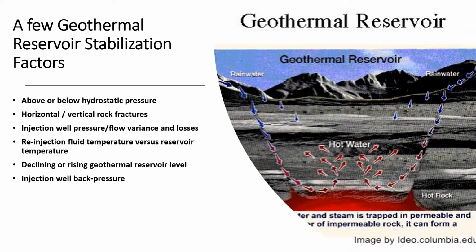Geologic structure impacts how the relationship between injection wells and return wells can best be managed. Injected fluids for reservoir replenishment and stabilization can be lost to fractures extending far beyond the intended production zone. This can be costly and additionally complicate pressure stabilization of the reservoir in the return well area.